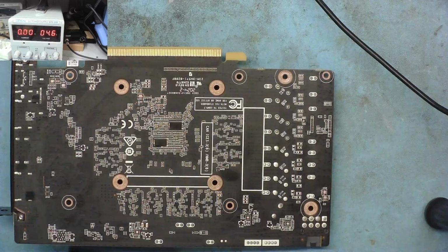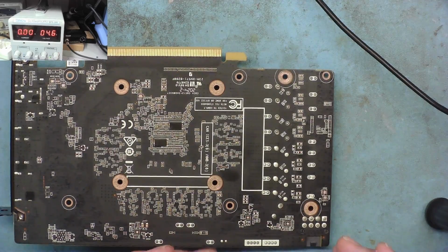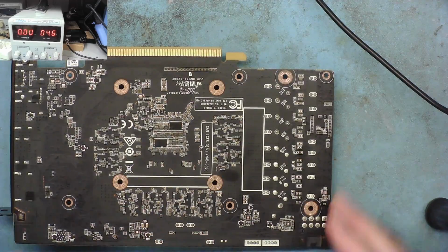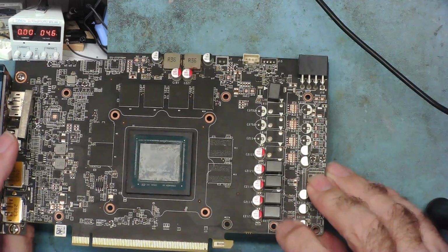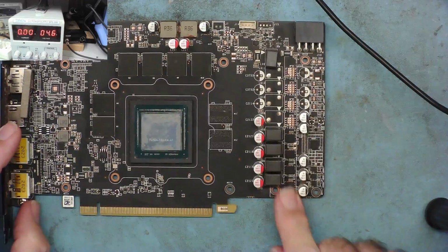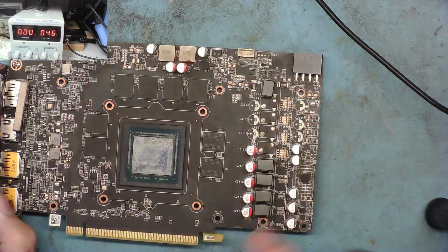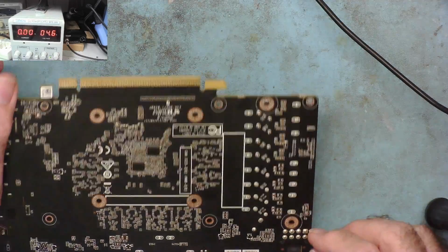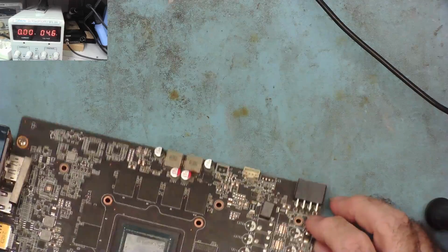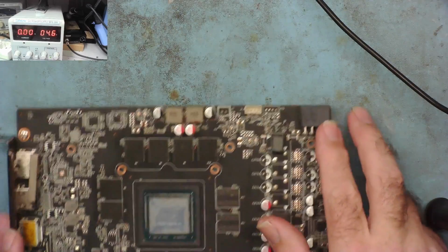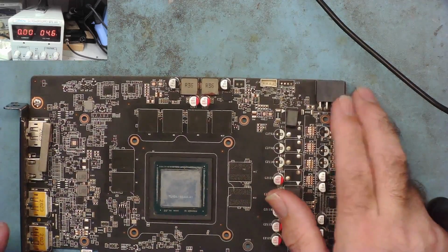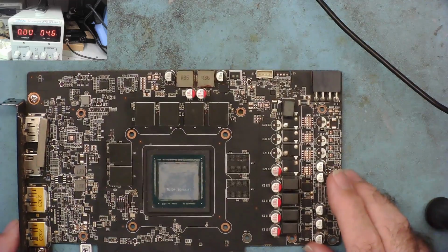Another very common method of short circuit finding that people use is voltage injection. Via this method, we inject a voltage into the short circuit to see what component gets hot. Now we know that all of the current is flowing through this MOSFET, the faulty one. We've already determined that by a few methods now, but let's see whether this method is going to work. So in this case, we need to inject 12 volts into here, connect to ground. That's what we normally do, 12 volts to ground, and see what gets hot.